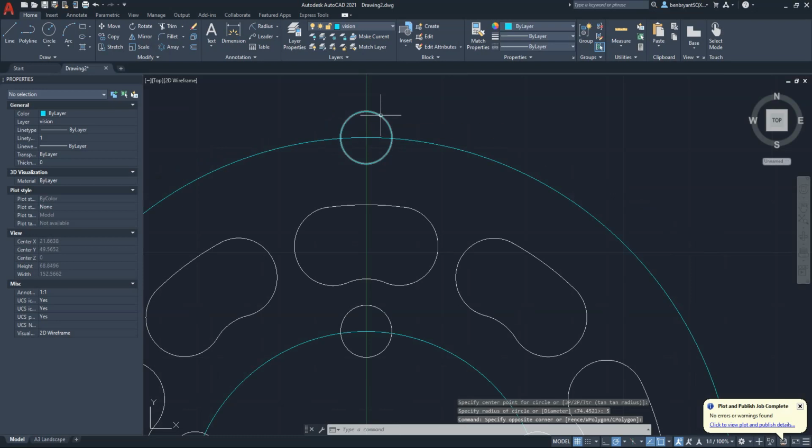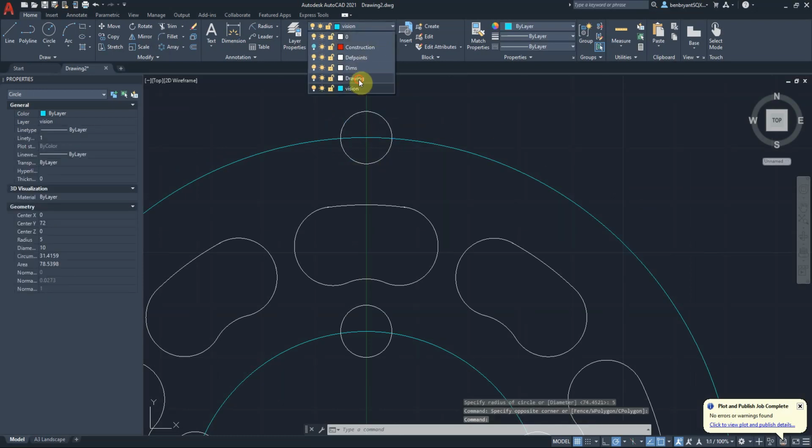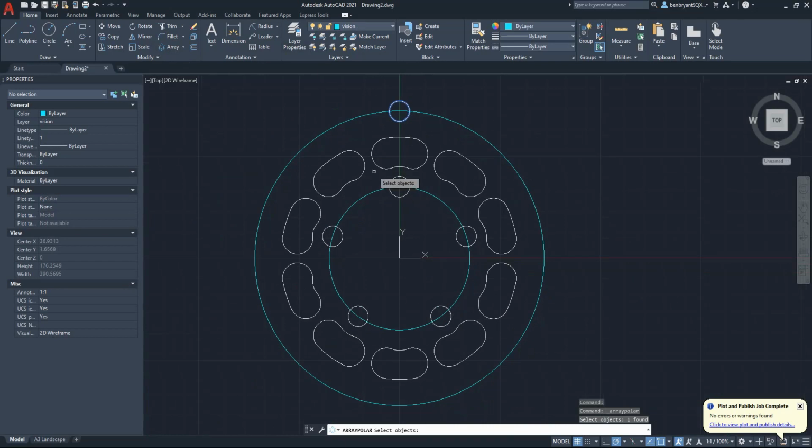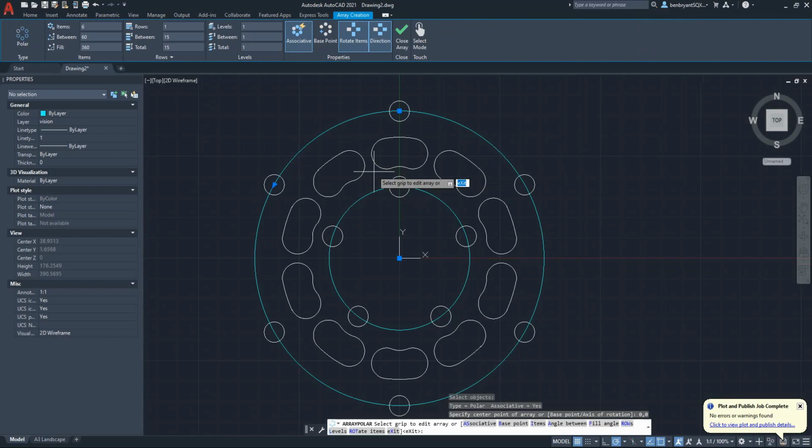Okay, I'm going to change these into my drawing layer, because once it actually does an array, you can't manipulate it unless you split apart the array again. So select my objects, 0, 0. I need 45 of these ones. So that array function now, 45.